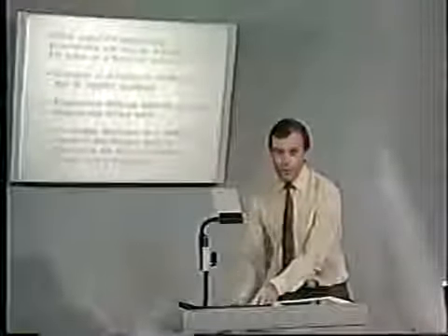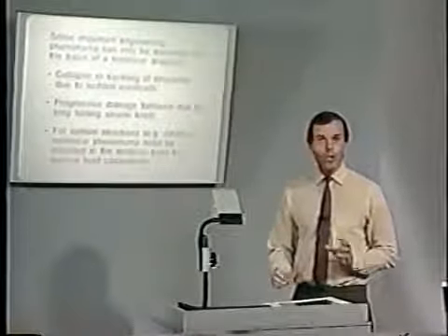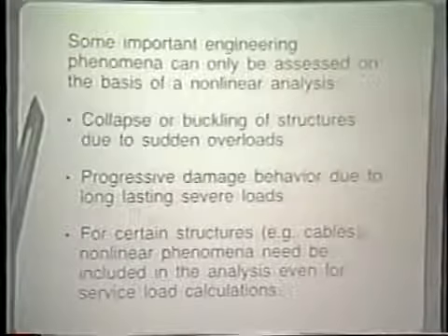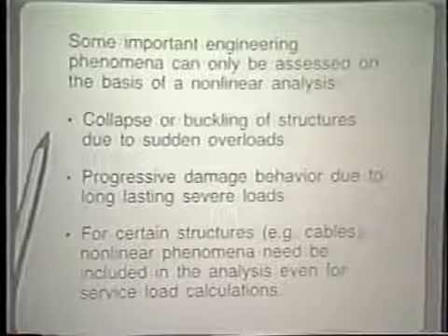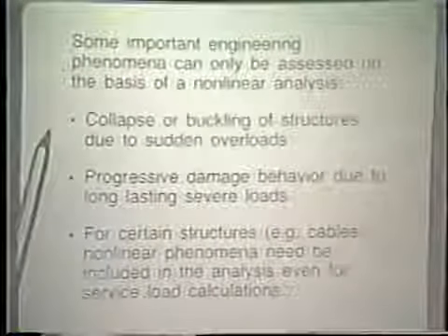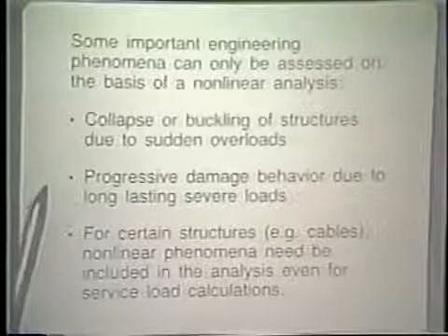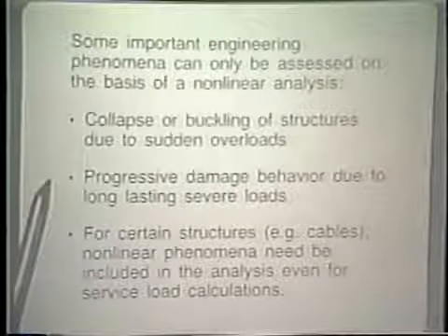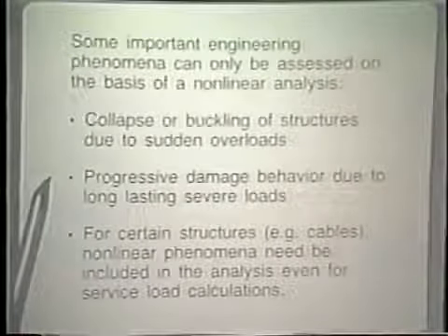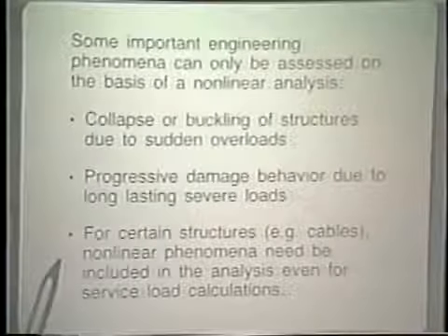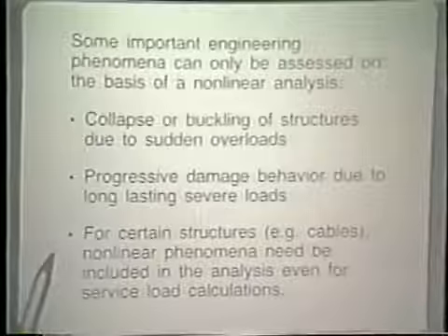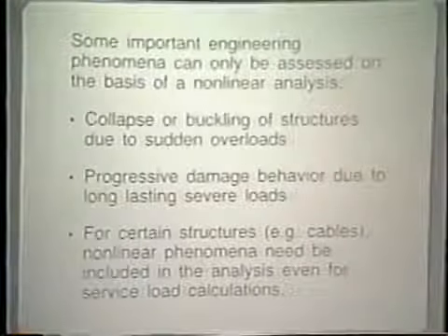Some important engineering phenomena can only be assessed using nonlinear analysis techniques. For example, the collapse or buckling of structures, due to sudden overloads. I'm thinking here typically of shell structures, say. The progressive damage behavior due to long-lasting severe loads, such as, for example, high-temperature loads in nuclear reactor components. And for certain structures, such as cables and transmission towers, nonlinear phenomena need be included in the analysis even for service load calculations.